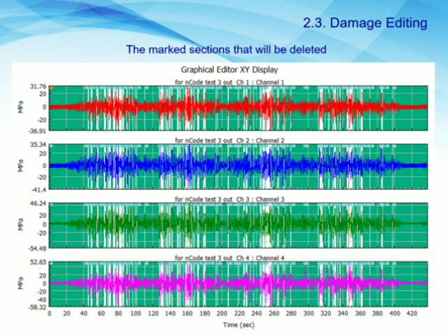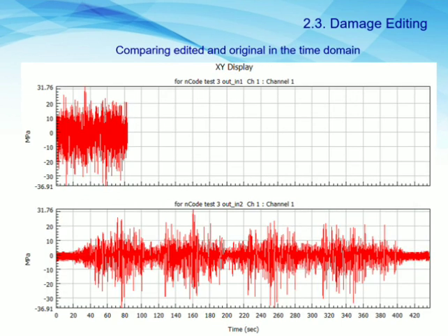In this slide, it's easy to see the effect of removing non-damaging sections in the time domain. The max and min values are the same and the cyclic content is the same, but the time duration has been drastically reduced. This will shorten the rig test time while retaining the important fatigue inputs, because these edited time histories are about 85 seconds long compared with the original 440 seconds.